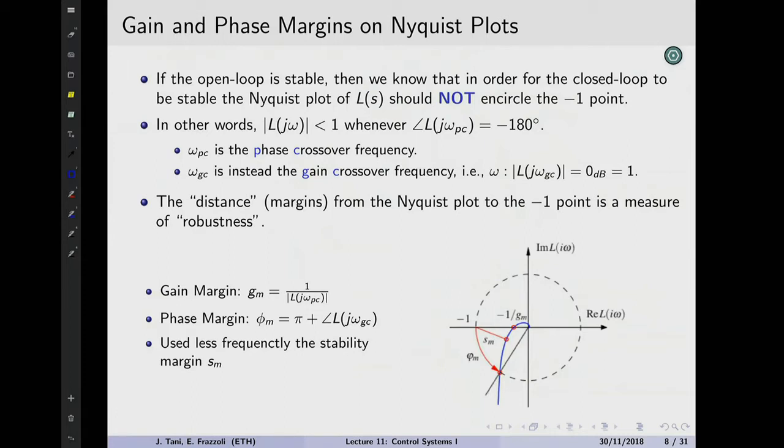But anyways, we saw that instability happens when the Nyquist plot transitions through the critical point, -1. And we saw that as k increases, the Nyquist plot basically becomes bigger, and at some point this transition happens because the Nyquist plot will cross the -1 point.